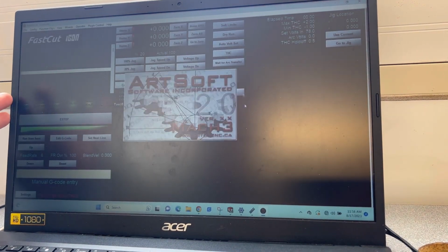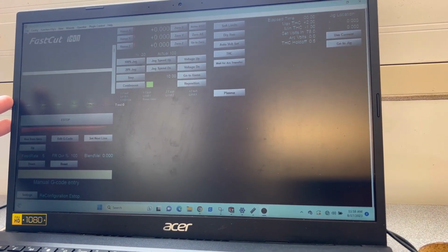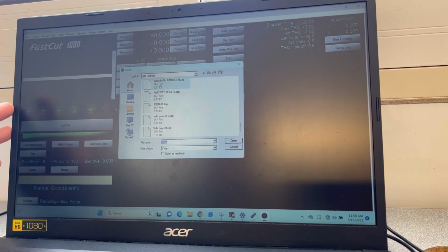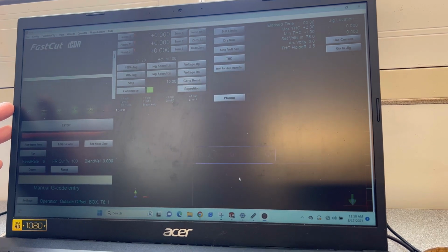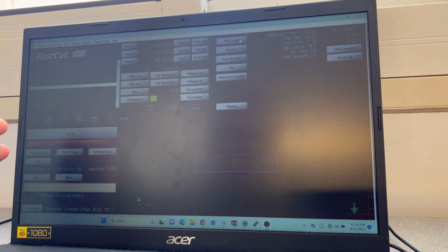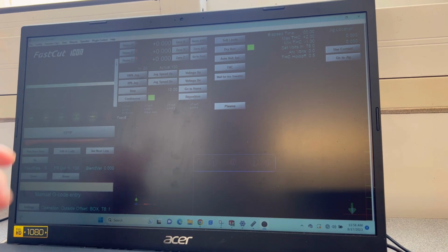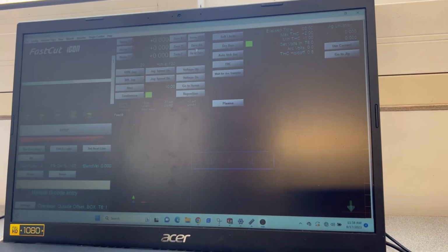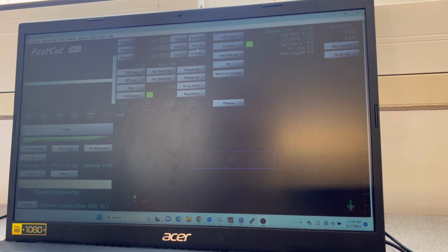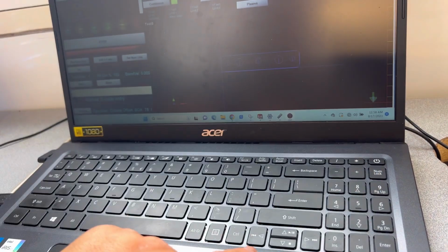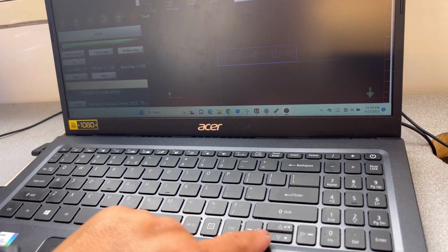Everything looks good. Click Load G Code. Named it Part with Holes. And there you go. You have your part now. And you want to turn on your dry run. You're going to home your machine. Then go to wherever your plate is. Zero all on the plate using your controls up, down, page up and down for the plasma tip, left to right for moving the table.